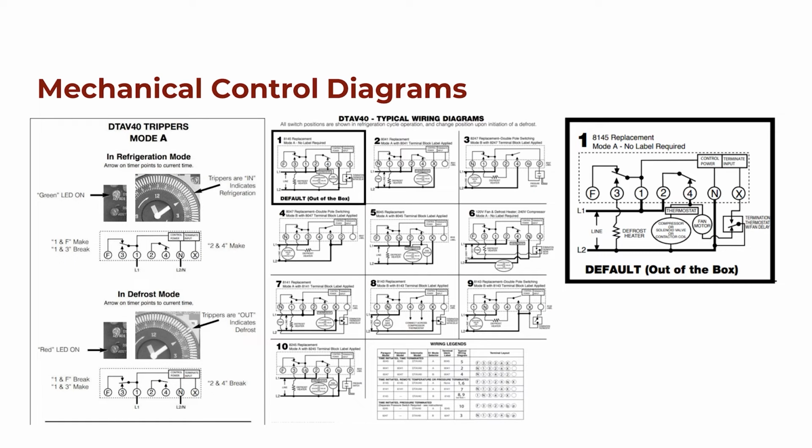That's going to be designed for us most of the time. But if we understand the sequence of operations, then we can reason out what's happening in a circuit in order to diagnose what's wrong and to repair it. Or maybe we do come into a situation where we have been hired to do the entire design and installation of a walk-in case. There's no engineering done. Well, we can figure that out and just follow one of these schemes and work with our refrigeration teams to determine which one of these configurations we should be going by.